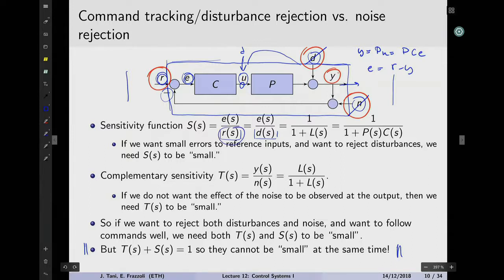Well, look, the transfer function between the reference and the error signal means, if I send as an input a reference, remember the reference is what you would like the system to actually do at the end, right? So if I send in a crazy reference, because that represents something that allows me to, I don't know, fly my airplane well, drive my car efficiently, or make a lot of money on the financial market, you want to make sure that the Y tracks the reference, because that's the objective here.